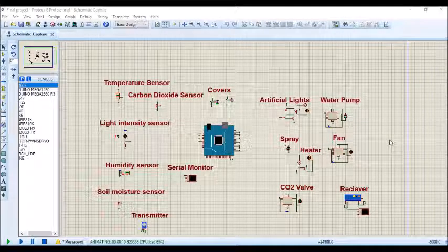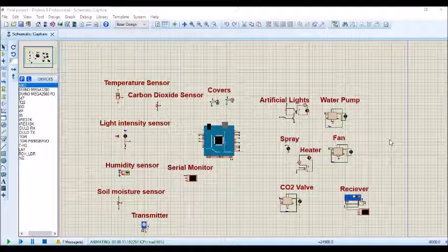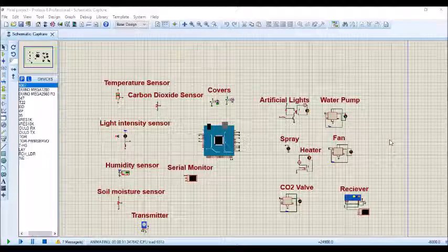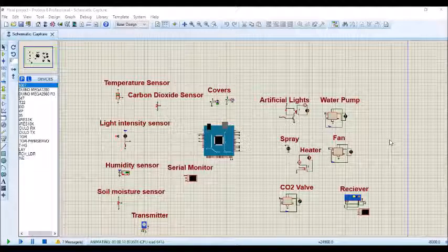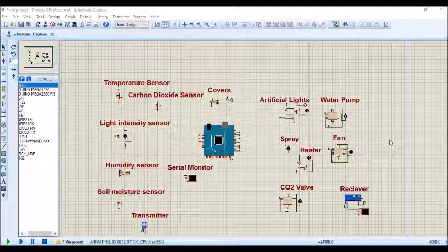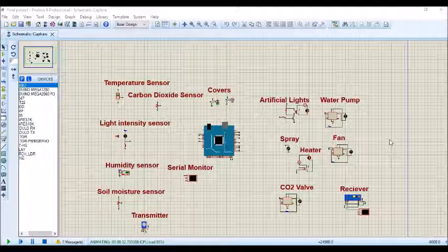The soil moisture level is controlled by water pump. When the water level is low, the analog voltage will be low in soil. The analog voltage will keep increasing as the conductivity between the electrodes in the soil changes. Hence, I have used a variable resistor which works with the same functionality as a soil moisture sensor. The major reason why using a variable resistor as soil moisture sensor is possible is because the probes in the soil moisture sensor are variable resistors in reality.